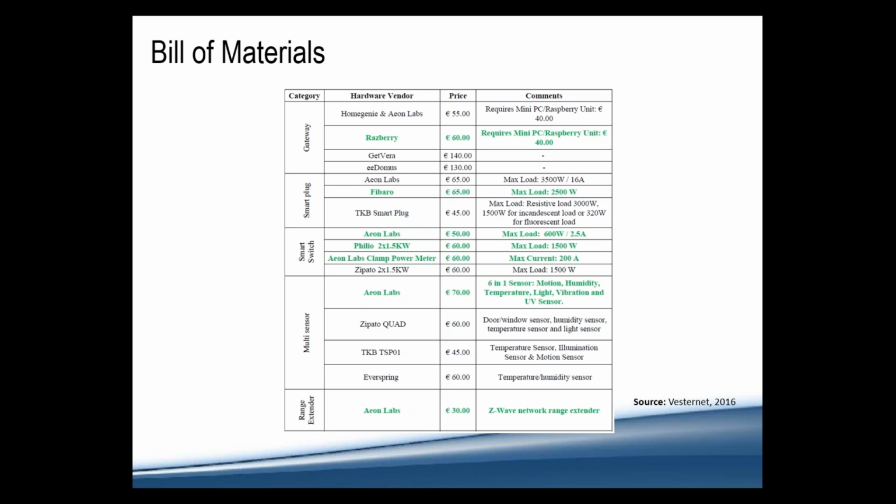Then, by having a quick review of the Z-Wave devices available in the bibliography, we selected the ones that best fit the different use cases examined in the project. Of course, as with any other wireless network, we need a gateway in order to communicate with the different devices. This gateway acts as the endpoint at the building level to report data to our application. With the gateway as the heart of the system, we selected smart plug devices for monitoring plug loads, and smart switches for monitoring mainly lighting consumption and also electrical HVAC consumption.